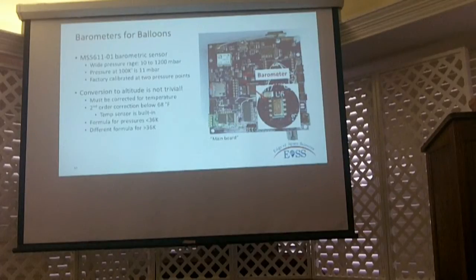And then I actually output the barometric pressure on the APR status string. So when this thing's coming down, if we lose GPS lock, it'll output the barometric pressure. So we can call the FAA up, who's real interested where the balloon is, or how high it is, because it's coming back through their airspace, they want to know. And so, we want to call them and be able to say, it's this high, oh, it burst and it's on its way down, and sorry about that. We lost our GPS.